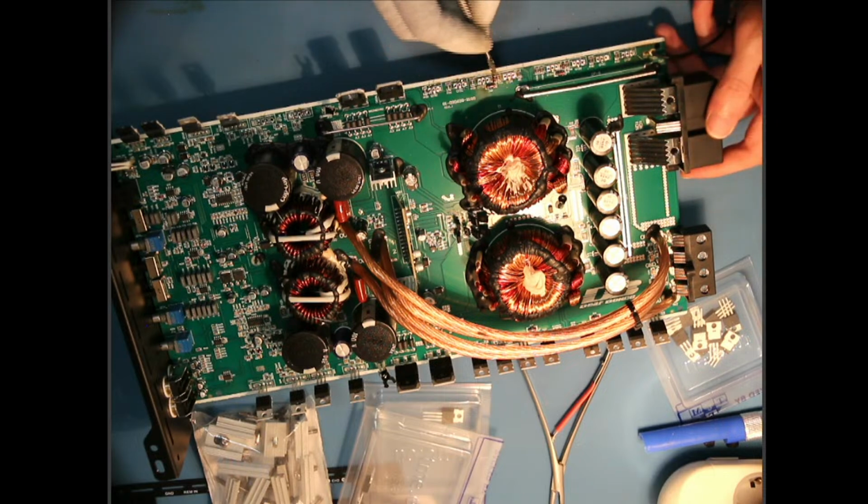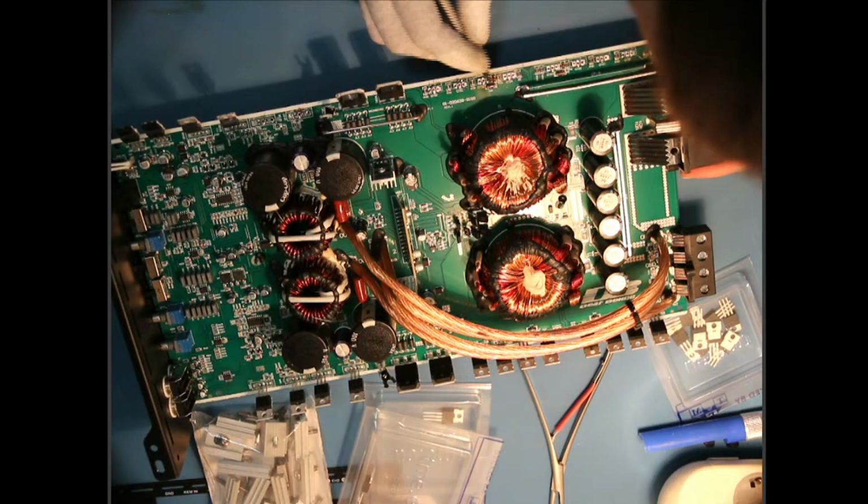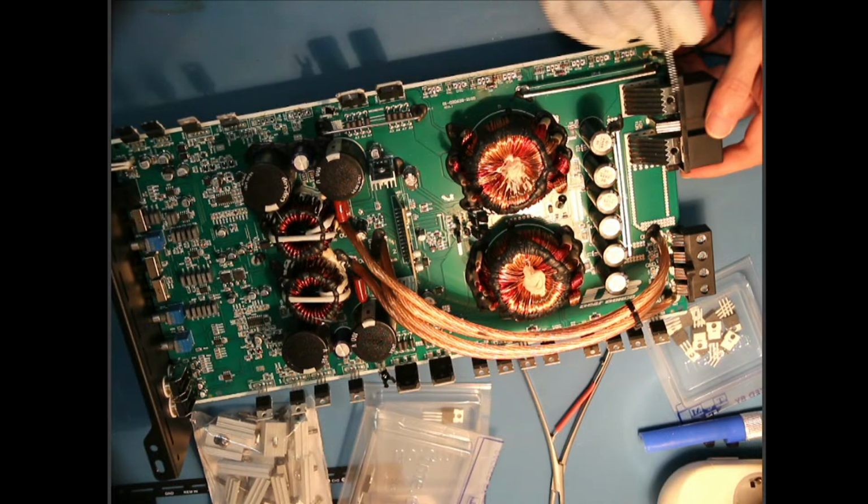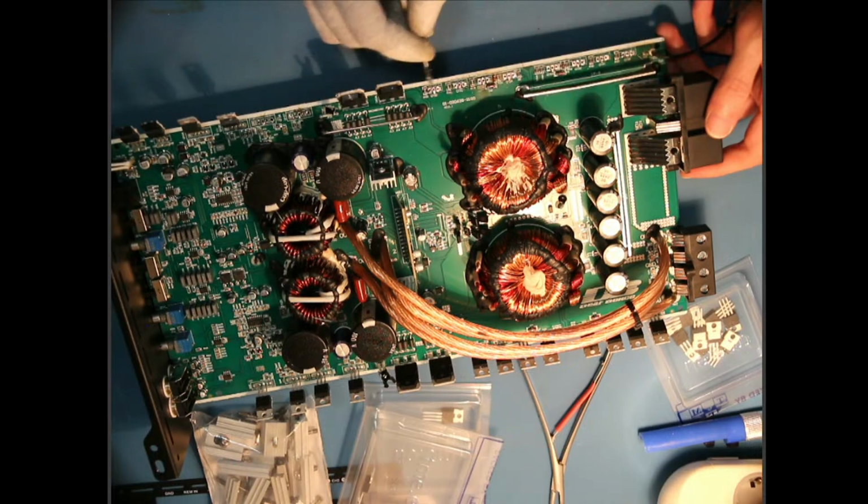The board's a bit toast here. It got really hot really quickly. So remember, never touch the plus 12 volt from your car battery to the signal ground of your amplifier or to any of the output terminals, because it's doomed.